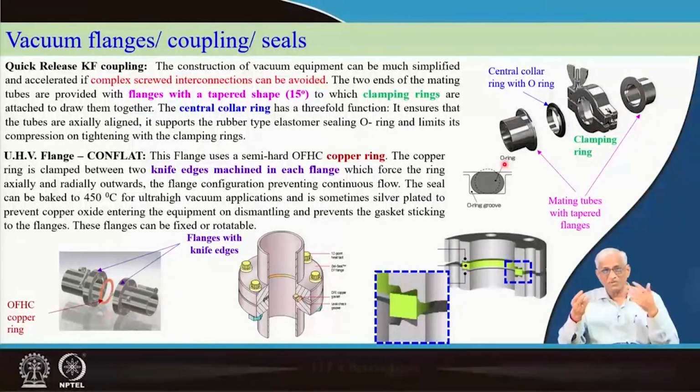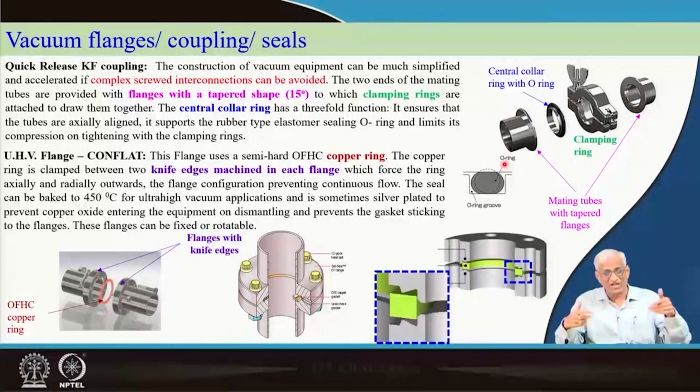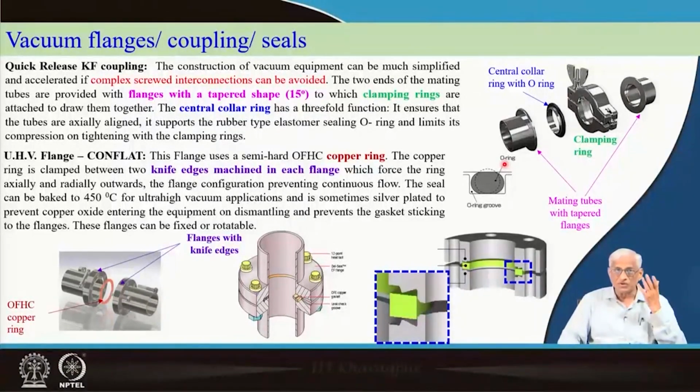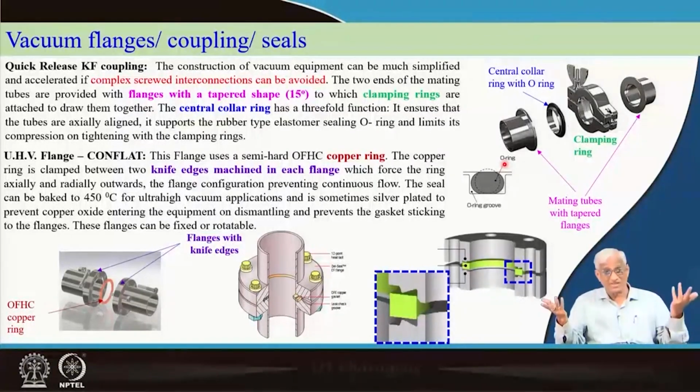For example, when you are making a thin film deposition, you require substrates, you require substrate manipulation, you require shutters, you require source materials, you require electrical feed throughs, you require a bell jar, you require optical window, you require a backing line, a roughing line, you require backing valves, roughing valves, air admittance valves, interconnecting flexible bellows, valves, seals, gauges. You have to be careful in choosing all of them.